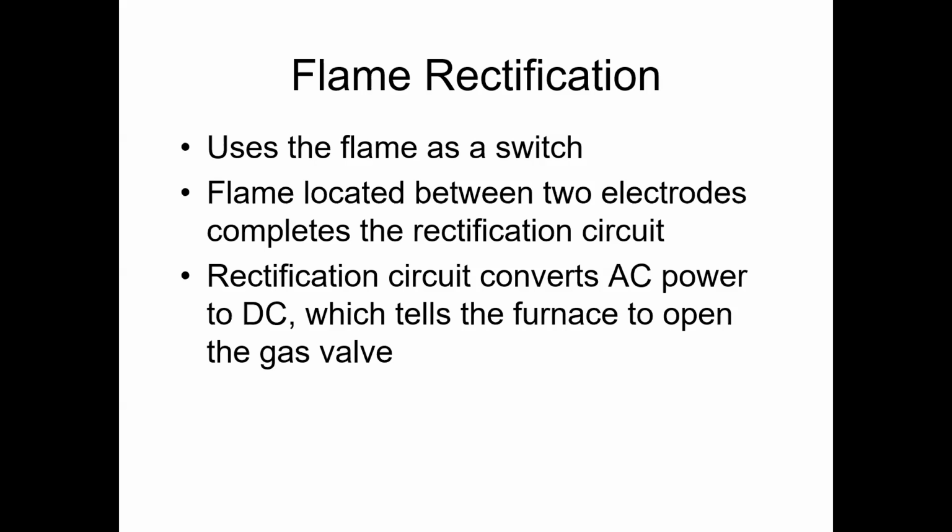So flame rectification, this is a newer style of flame proving device. It's not just going to send a signal of voltage, like you had with a thermopile, or a thermocouple where it's sending millivoltage.